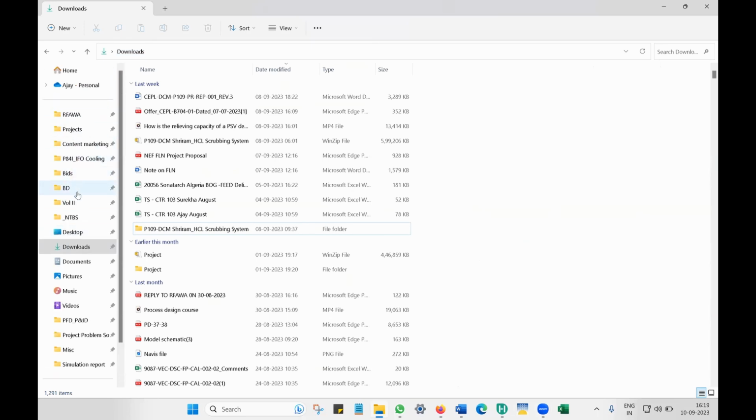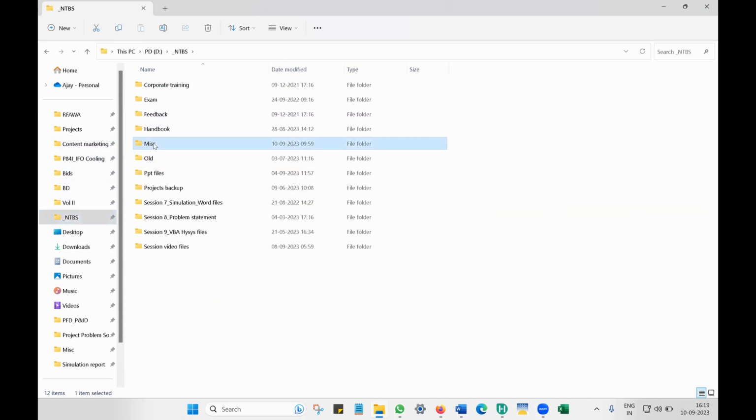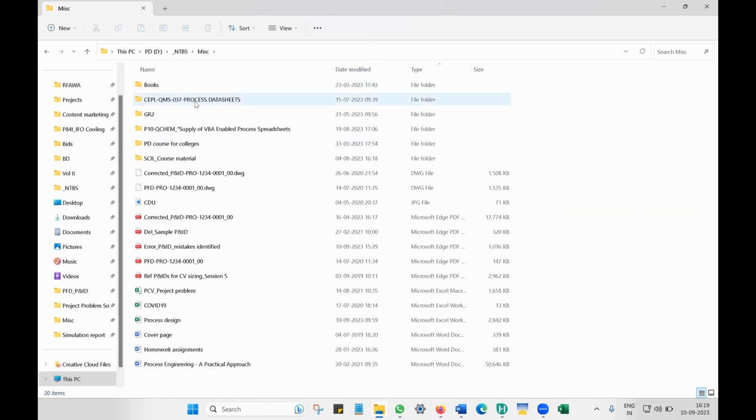Okay. So basically, the peak point of HYSYS or rather VBA is how to connect HYSYS with Excel and vice versa. Right? I'll just try to open one file. Is there any way we can create HYSYS as a DLL, so that when we run from Excel, we don't open HYSYS, but it runs completely from Excel? I don't believe that is possible. You have to have the HYSYS application. Okay.